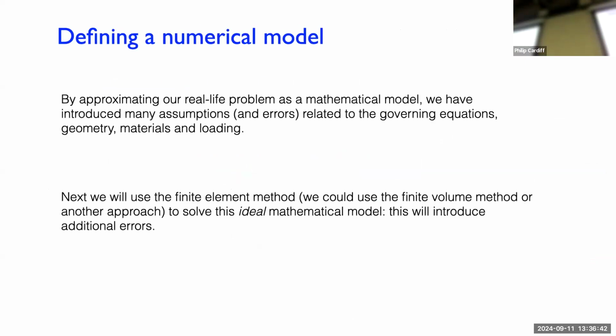So we made our maths model. Next, we have to make a numerical model. And this is where we use the software. If we use the finite element method, it could be Abaqus or one of various other software packages. Note though that when we use a numerical method, like Abaqus, best case scenario, we get the answer to the mathematical model. We don't get the answer to real life. If you just started with the wrong mathematical model, Abaqus is not going to make magical predictions that coincide with reality. So best case scenario, your numerical model will give you the answer to the mathematical model. Whether that is useful in reality or not depends on how you define the mathematical model.